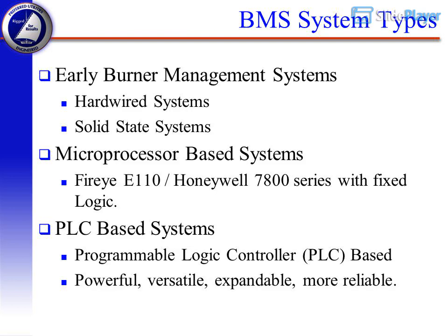BMS system types. Early burner management systems: hardwired systems and solid-state systems. Microprocessor-based systems, such as the Fireye IE110 and Honeywell 7800 series with fixed logic. PLC-based (programmable logic controller) systems are powerful, versatile, expandable, and more reliable.